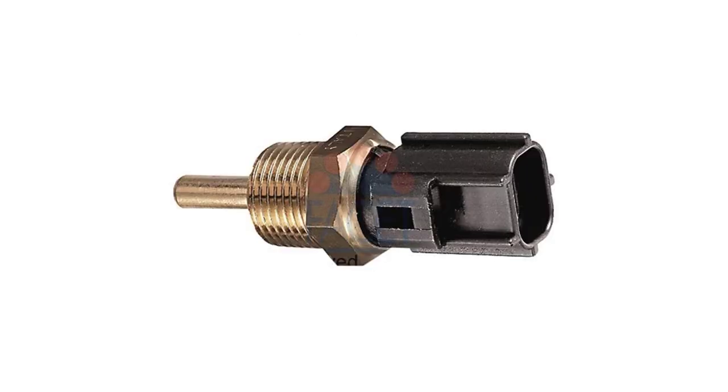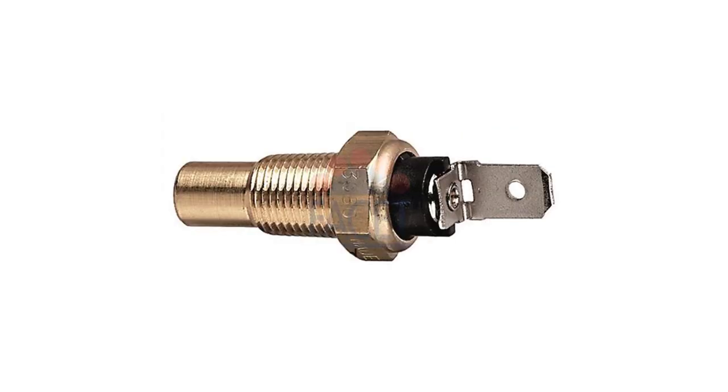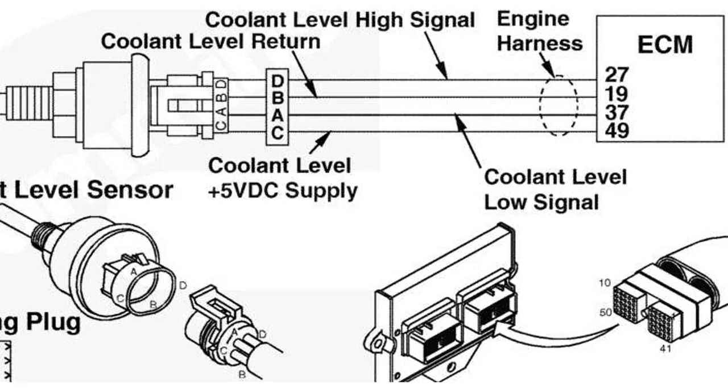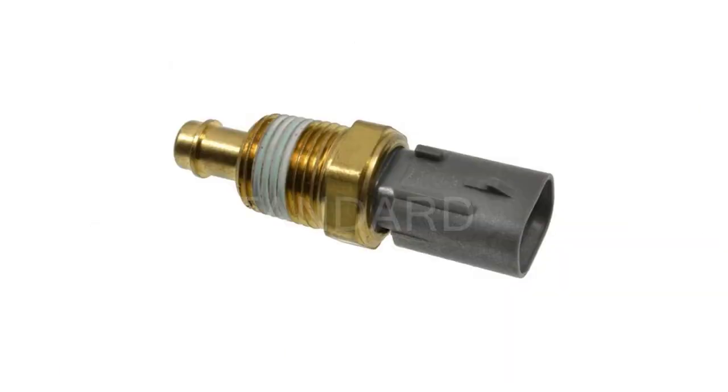The next step is to check the wiring harness. Inspect the wiring harness for any damage, corrosion, or loose connections. Repair or replace any damaged wiring or connectors. Step 3. Check the ECM if the engine coolant temperature sensor and wiring harness are both in good condition.